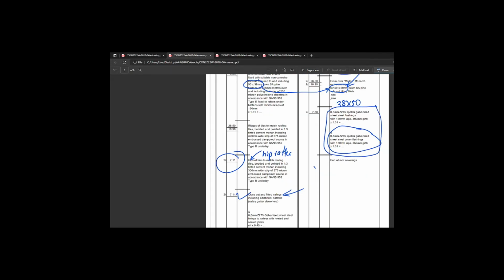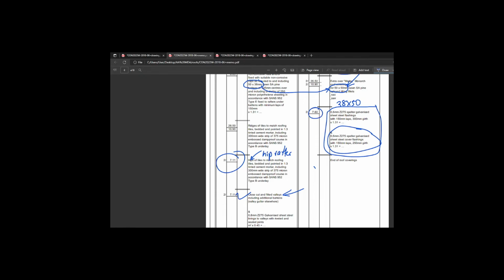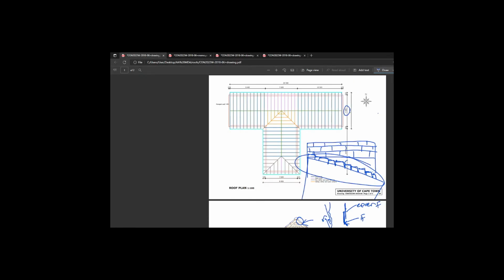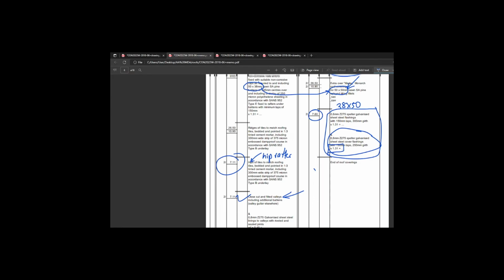We have brickwork meets roofing, okay? And what happens here is it's taken, let's just take a look at the dimension, 7.60, 7.60. What's convenient about that dimension is that it goes right up to the edge of the brickwork, and again right up to the edge of the brickwork. So you can take that. It's very important you apply your multiplier to go from plan to sloped. So from plan to slope like this is simply 1.31. Okay, happy? Good.